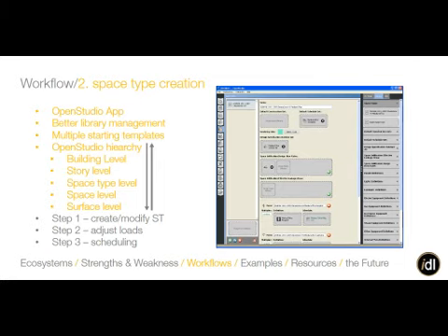However, let's say with Office, they really only have Office and I think Corridor, and I think that's it. So if we want to do conference room, high level, low level, medium use, then we have to actually modify those space types or create new ones, which we would do in the OpenStudio application.